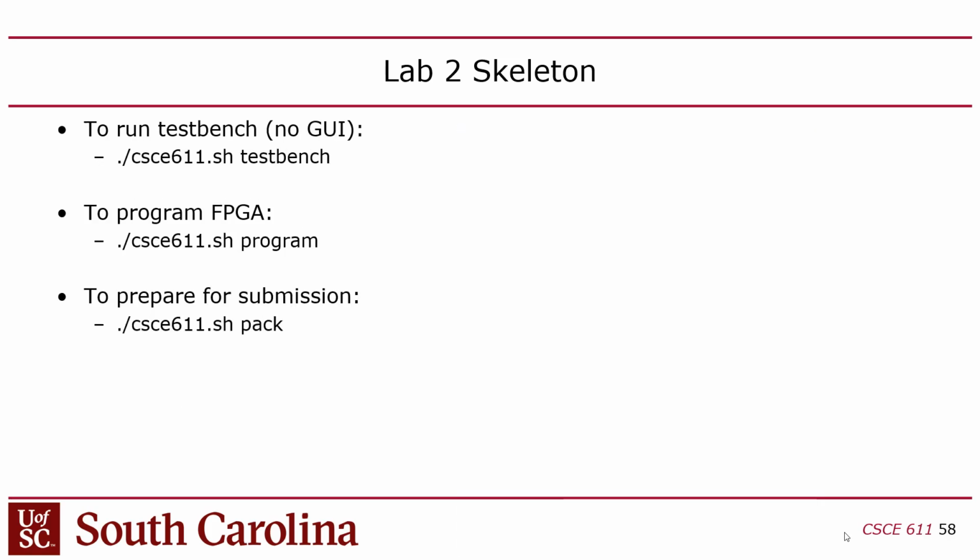Oh, sorry, here it is. Yeah, these are the commands, sorry. Test bench, program, and pack. Now, one of the problems with test bench is, I have a whole sequence of slides on test benches, but I mentioned that the test bench does everything. These commands are all command line driven, right? What that means is that if you run the test bench command in our script, it doesn't bring up the ModelSim GUI.